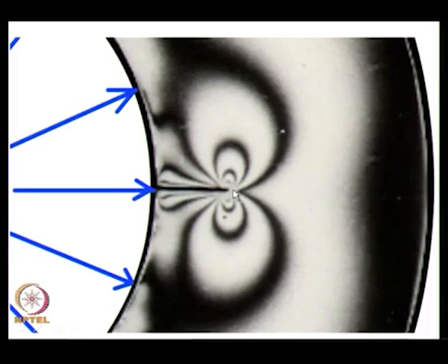And this observation is quite important for an experimentalist. See, when you have a crack, in the immediate vicinity of the crack the stresses would be very high and you will have plastic deformation. You really do not have mathematical equations to fully capture what happens exactly at the crack tip. From an experimental point of view, you will not be able to go close and collect data. You have to collect data only from a region away from